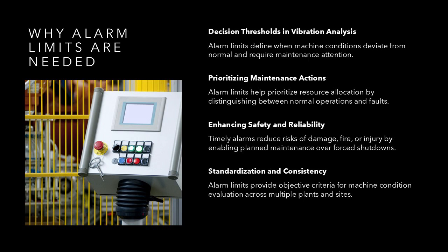Additionally, alarm limits support standardization and consistency across plants and sites, ensuring that machine condition is evaluated using objective and repeatable criteria rather than subjective judgment. Properly set alarm limits therefore form a critical link between condition monitoring data and maintenance decision-making.